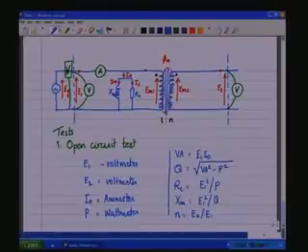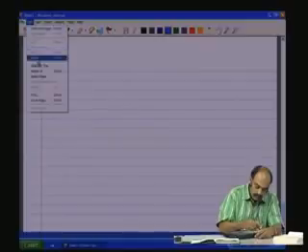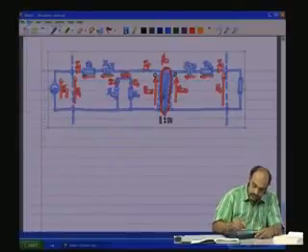These measurements could be taken around 5 times, and an average of that found out, and that could be used for making the calculation here to improve the accuracy of the measurements. So, now we have obtained the core loss component, the XM, which is the magnetizing component, and the turns ratio from the open circuit test. We now perform the next test, which is the short circuit test.